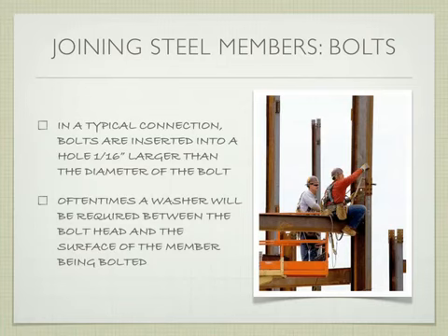Okay? So to span that little bit of a gap, a lot of times there's going to be a washer that's going to go in. The bolt that I already passed around to you has a washer on it, and I'm actually hoarding these bolts on purpose because I need to explain a few things about them. But the washers allow you to bridge that gap, cover up that hole, and give you a little bit more bearing surface to attach.